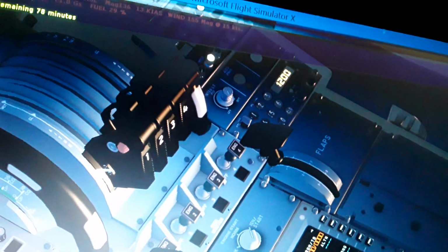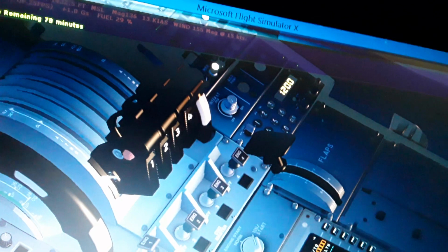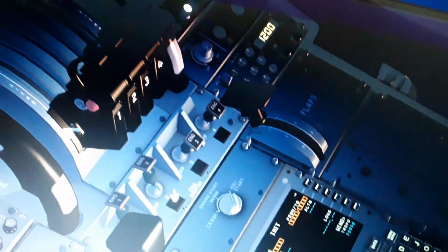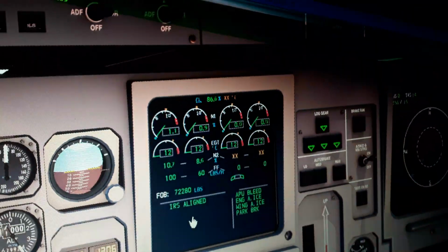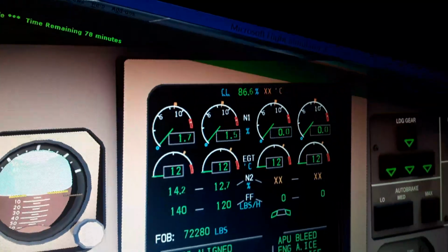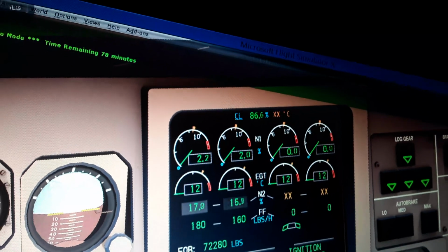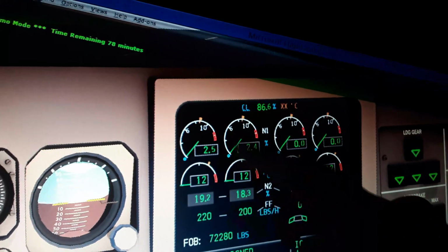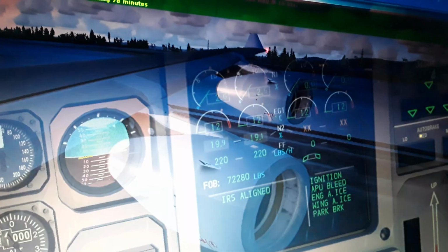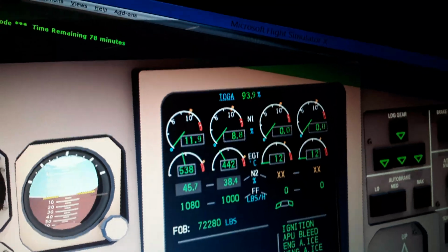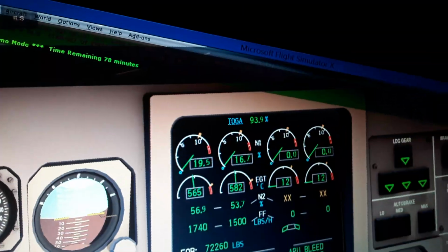So I'm gonna turn the engine start mode selector here, and I'm gonna turn both engine master switches, which is gonna let the low and the high pressure fuel flow valves on when the engine starters are having high pressure, like N2 of 20%. And here we can see the engine spinning. It also initiates the FADEC, which is a full authority digital engine control. So I'm gonna do very fast.